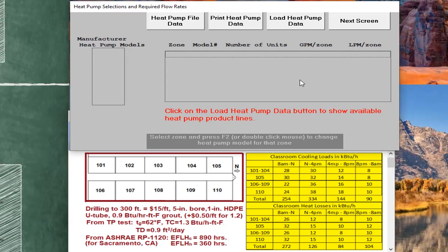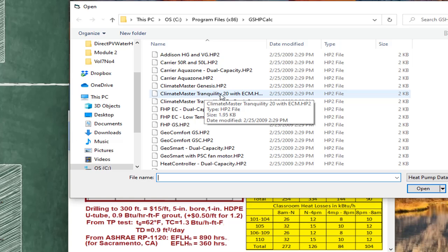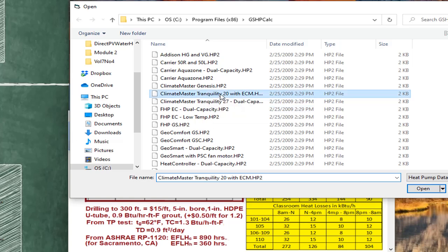Even more important is that the ratings don't contain the power used by the fans to any large degree, so it must be entered so that we correct these heat pumps and get the proper performance. And so all of these have been corrected for those two things. Okay, so now we're going to select a series. We're going to do kind of a middle-of-the-road heat pump. We'll pick this one right here.